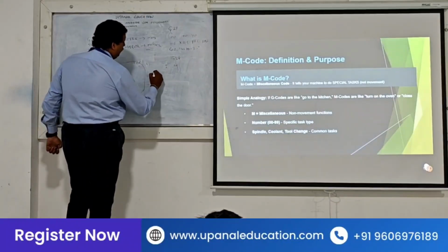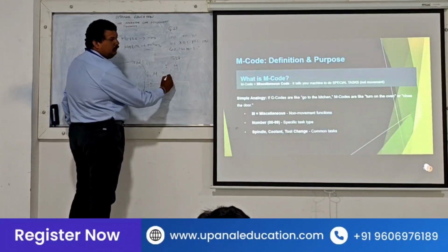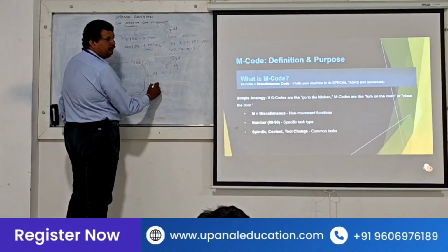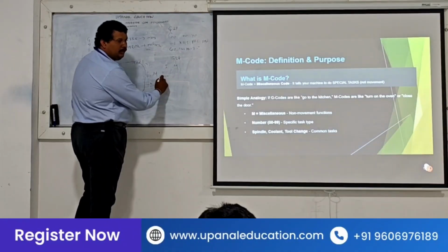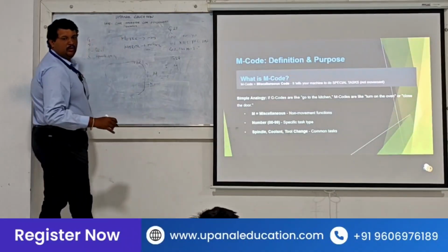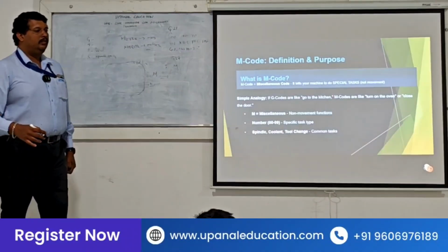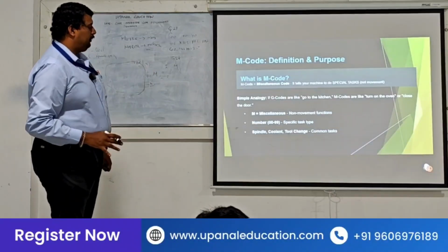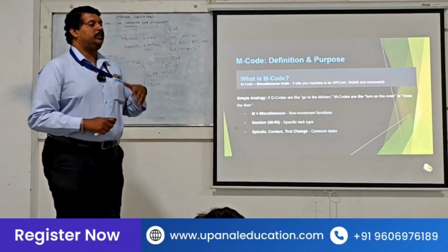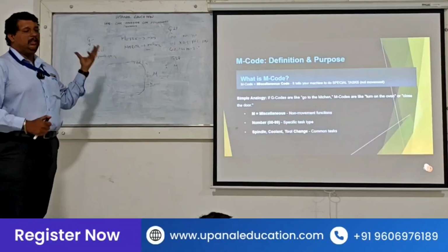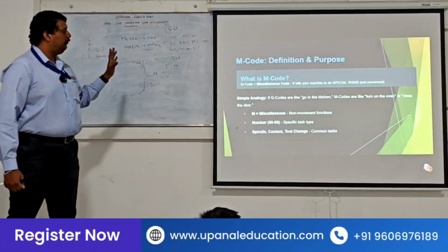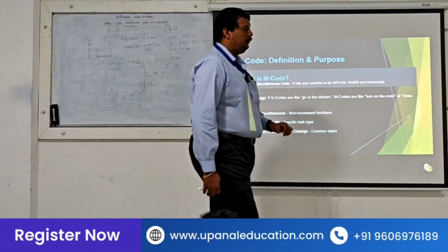So what is the specific format for this? Let's check how we put the G. This will be a capital letter M followed by the code: M01, M02, M03, M04, M99. The M comes here. Okay? This is the main common task, like tool change, spindle on, coolant on. All these things will come in M code.